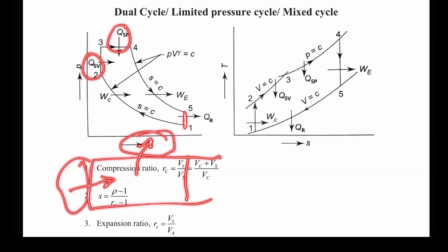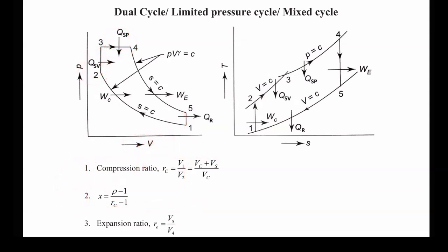There will not actually be heat transfer because of combustion in this process, because this is an ideal process, air standard. And if you see the cycle, it is a closed loop. So whatever air is there inside the system, it is not going to move in or move out. The air inside stays while the piston reciprocates, and we will be having this cycle.